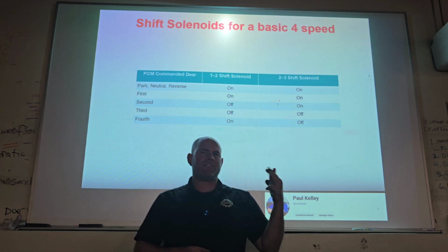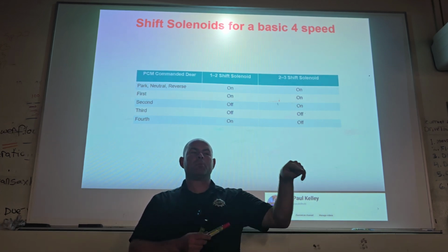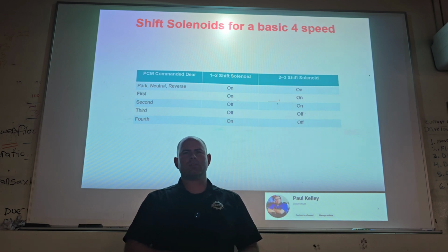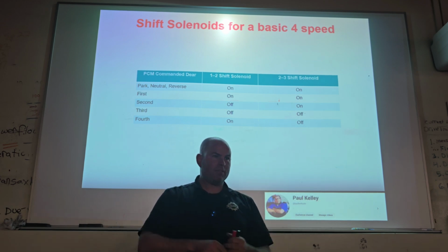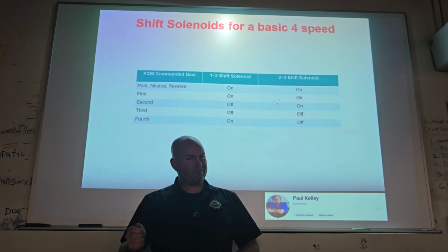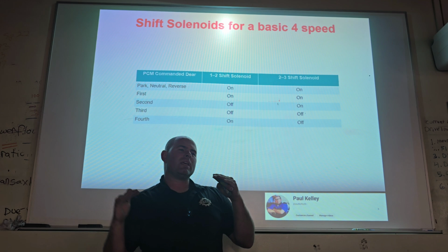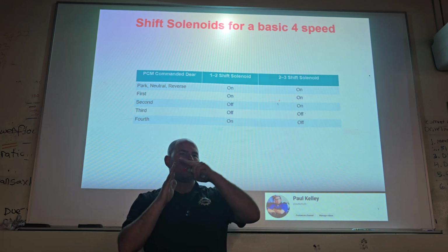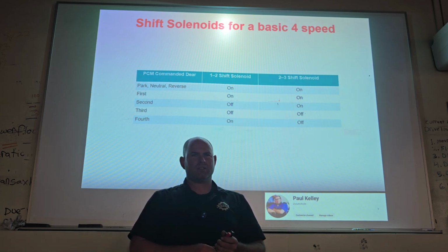In this case, I found out the TCM gets its power supply from a relay. I literally just back probed the TCM right there in the driveway and said, oh, the TCM's not getting any voltage. And then I back probed it again and I found out the relay's not putting out any voltage. It could be, but it started fine. Yeah. But then I back probed going into the relay. Going into the relay had 12.6. I like that. 12.6 was good, but coming out of the relay, it had 0. What's your diagnosis? The relay.